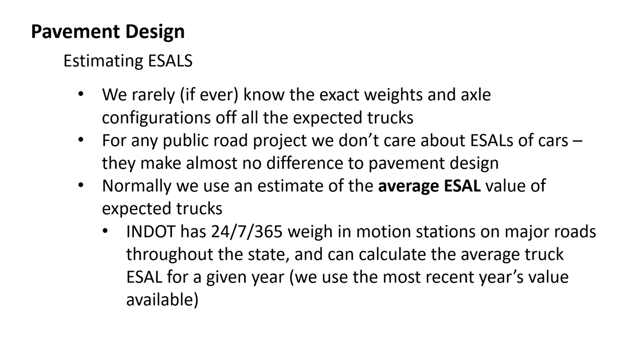Buses are another class. But in general, commercial vehicles can be aggregated, and if you know what your truck percentage is, we can tell you what your average ESAL is for all of the trucks in that group of categories. It's usually more in the single FHWA category, but in the truck category, we can give you an average ESAL value for those expected trucks. And that's what we normally work with, right?